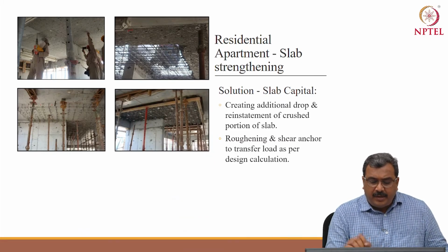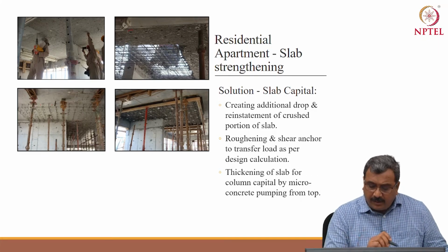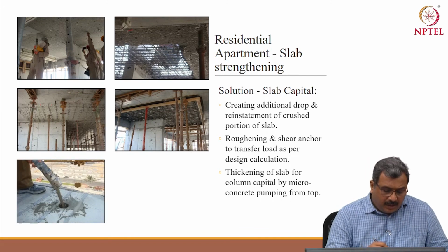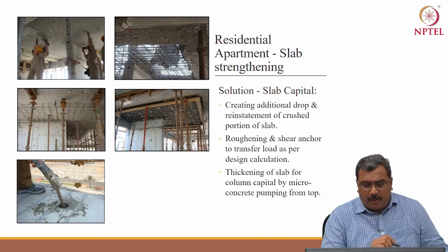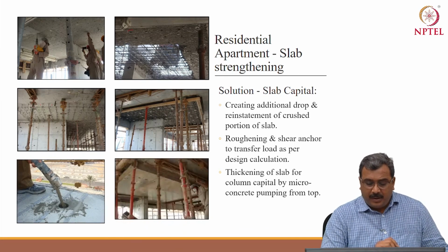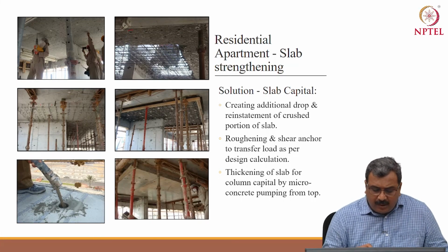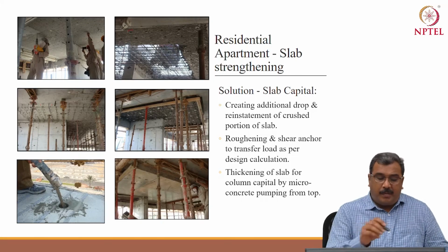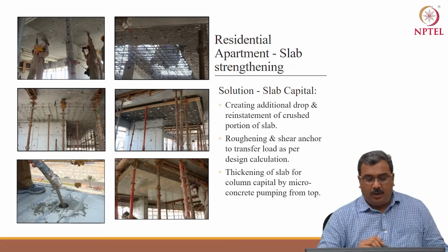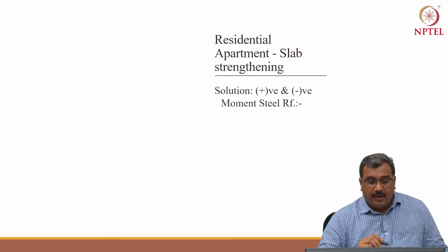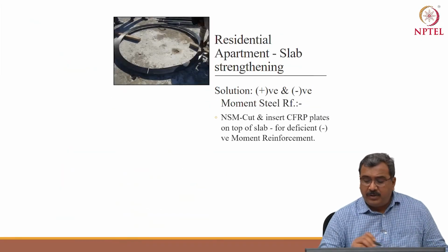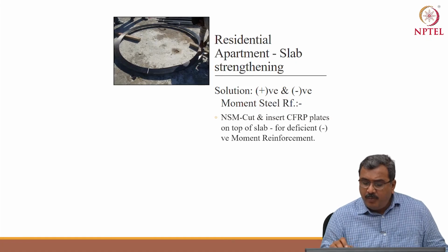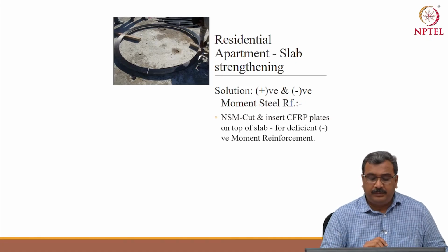Proper shuttering has been done, closed from the bottom, and the micro concrete was pumped from the top. And this is how the column capital looks after completion. So additional capital was incorporated. Now the second requirement: to suffice the positive and the negative moment reinforcement deficiency.